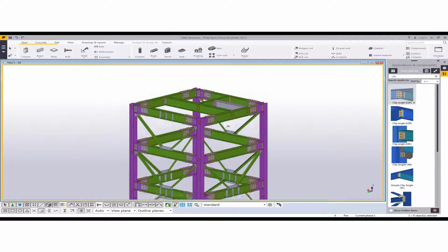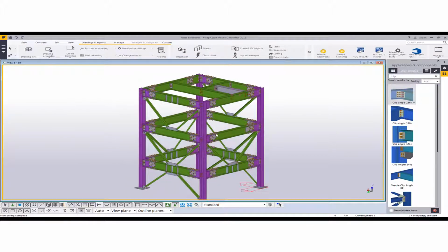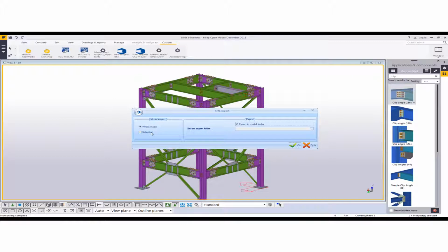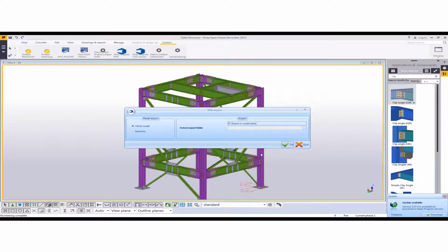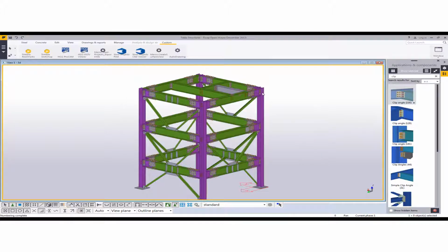Okay, the next step is we want to link that down to the Steel Projects PLM software. There is an application we can download from the warehouse or from Steel Projects Direct, which exports the data out. This creates an XML file. For us in Tekla it's quite simple, it's just a one-click production. So we click on the model, say OK to that, and it produces the data directly to go to the Steel Projects PLM software.